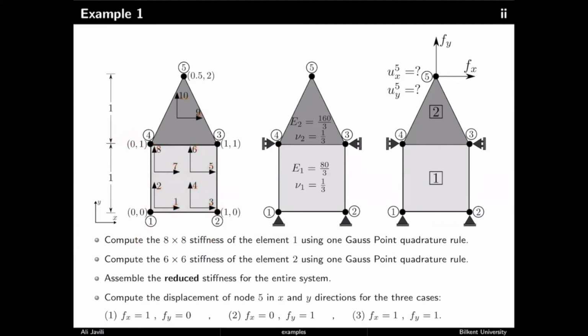These are the degrees, but they are not the degrees of freedom. The degrees of freedom come later because of the constraints, but these are the degrees that you need to start with. I want you to write your stiffness exactly with respect to this, because if you don't do it, it's almost impossible for me to check it. There would be so many different variations. So you must pay attention to the particular numbering of the degrees and node numbering.